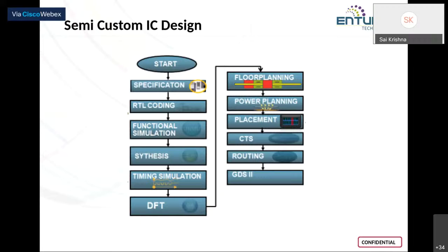Yes, so you have Conformal, which deals with logic equivalence check. And just to give you an idea, LEC is a process of checking whether the design from 2 different stages, that means let's say your RTL code and the gate level circuit after synthesis, are both of them the same as per the logic or not, or the gate level circuit after your synthesis and the one after routing, are both of them carrying the same logic or not. To check that, we perform LEC in the Conformal tool.